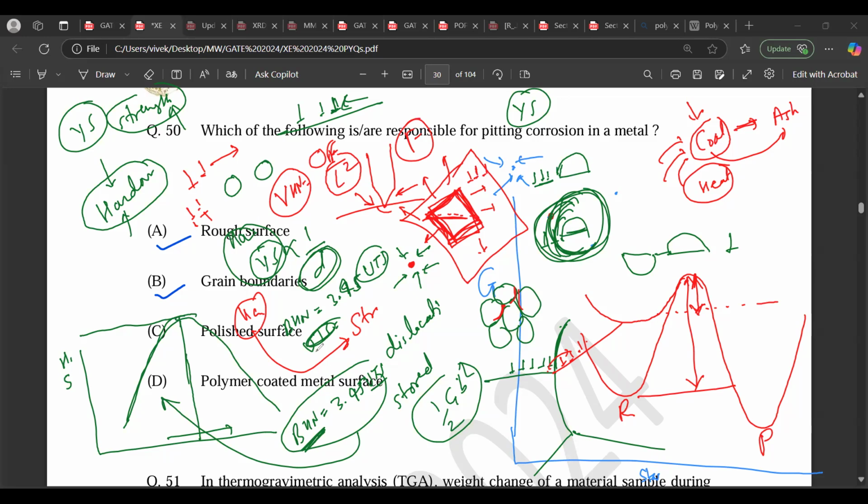Now my question is, why am I discussing all this dislocation phenomena? Because the dislocation is carrying stored energy, and that is very important. Dislocation is carrying stored strain energy, because a dislocation is fundamentally nothing but a defect, right? So your material is distorted along the dislocation. Here the atoms are closer to each other, here they are farther from each other.